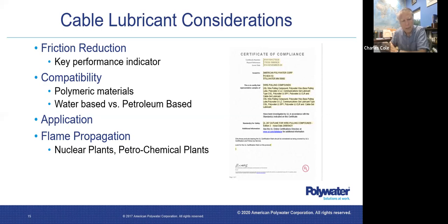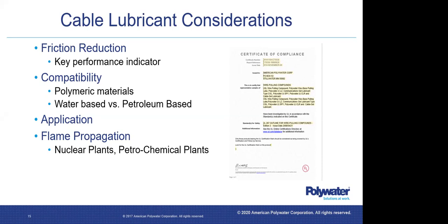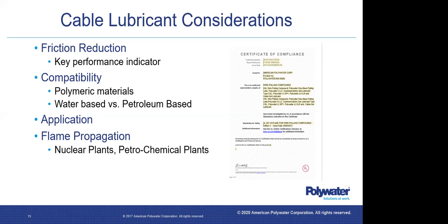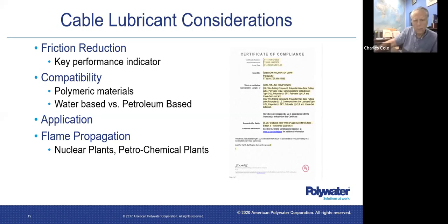Probably 85% of people that use lubricant will do it that way, but you could also pump or use what we call a front end pack, plastic bags of lubricant that will deploy the lubricant deep inside of the duct. Then flame propagation is also a very, very important factor to consider, especially if you're talking about nuclear plants or petrochemical plants where the issue of flame propagation is important to understand.